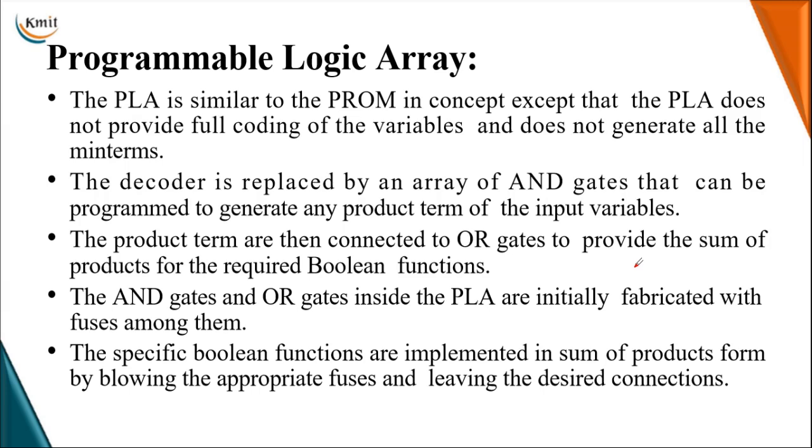So like this, you can program your OR array as well as your AND array. It is really similar to your PROM, the only difference being that here you don't have a decoder like in the PROM. If you have a decoder, each decoder output will be one minterm, which is considered a fixed AND array, whereas here in the programmable logic array, you have an array of AND gates where all inputs of the AND gates are programmable, and the OR inputs are also programmable.